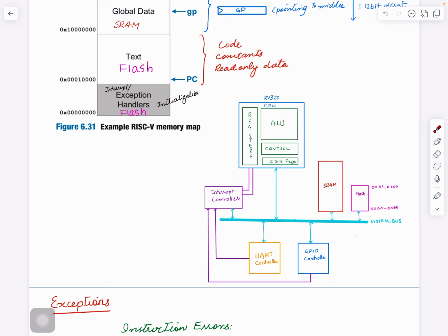There are also registers that the CPU can write, and then the output controller, based on what is written, will generate some output. So this controller's function is to manage the communication between the external interface and the CPU system bus. Correct? And those registers will have an address.